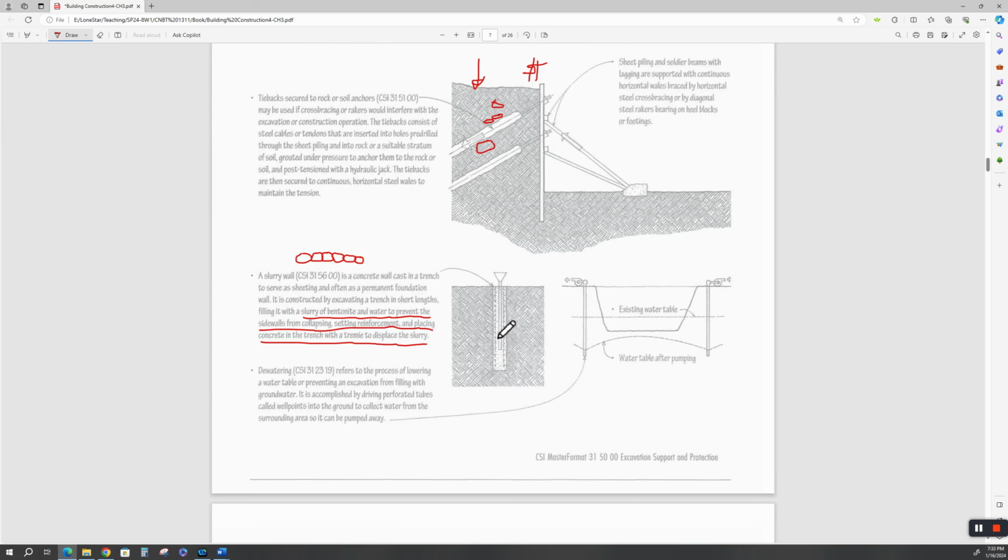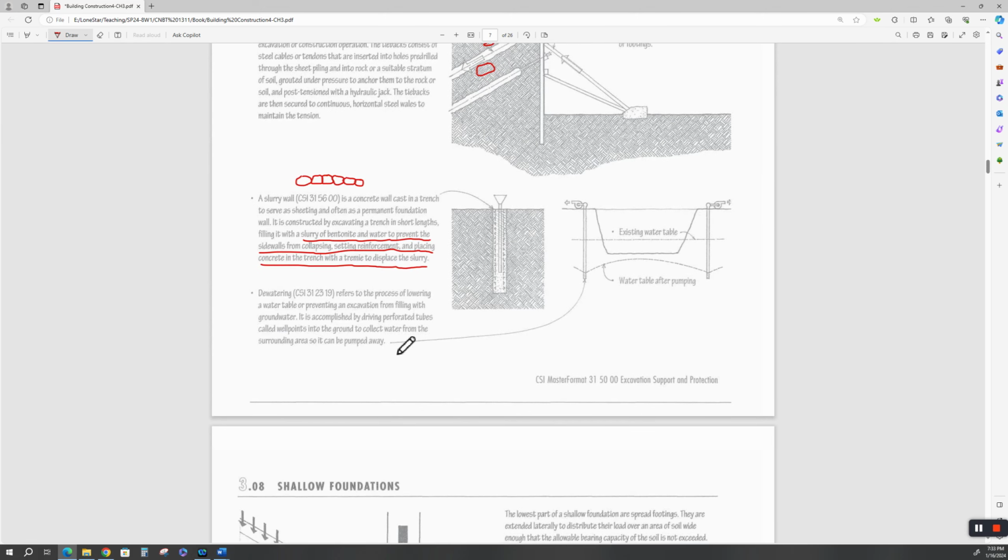All right. Now, we talked before about lowering the water table with a well point, and I don't remember if I actually used that term in that first couple of videos, but this is a well point system. All right, I told you about the straw that you stuff down, you drill down into the water table, and you hook pumps to it, you suck it out, and you draw the water table down.